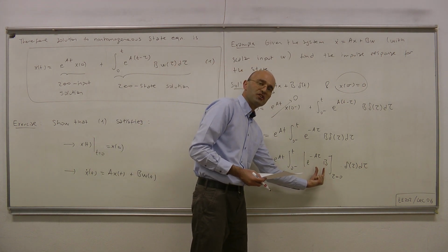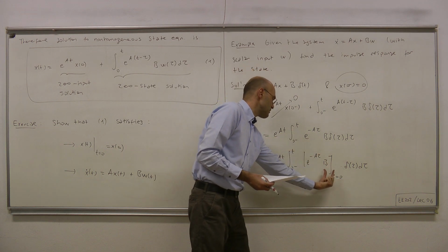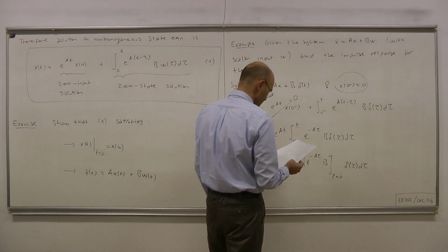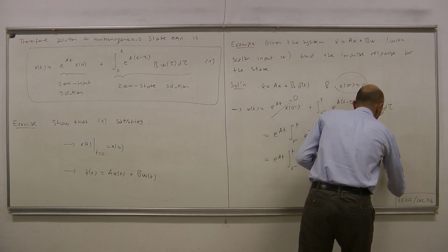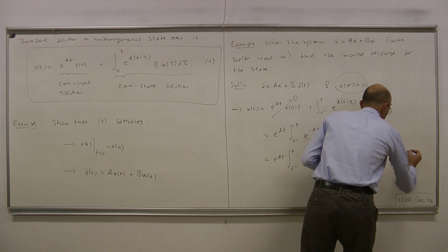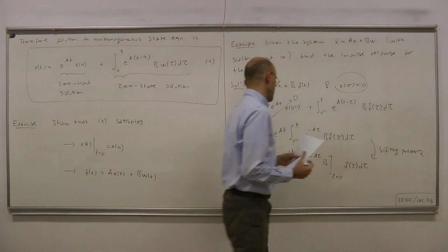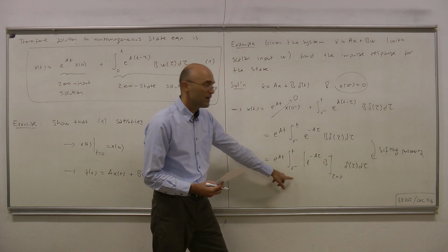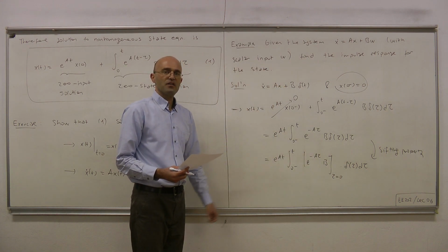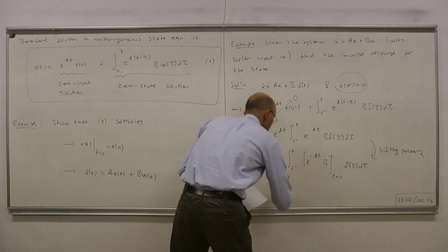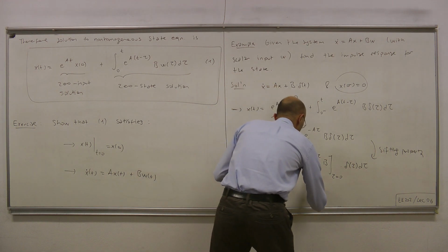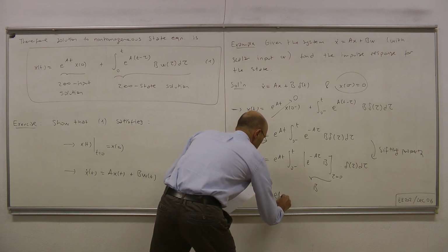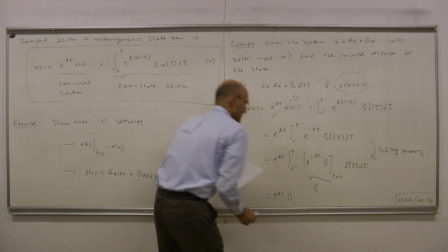Therefore, we're talking about a constant matrix, a constant vector. That means we can take it outside the integration, by the shifting property. And when you take B outside the integration, what remains is the integral of the impulse function, and the result is 1. So this thing here is B. Therefore, the overall answer is e to the At times B.